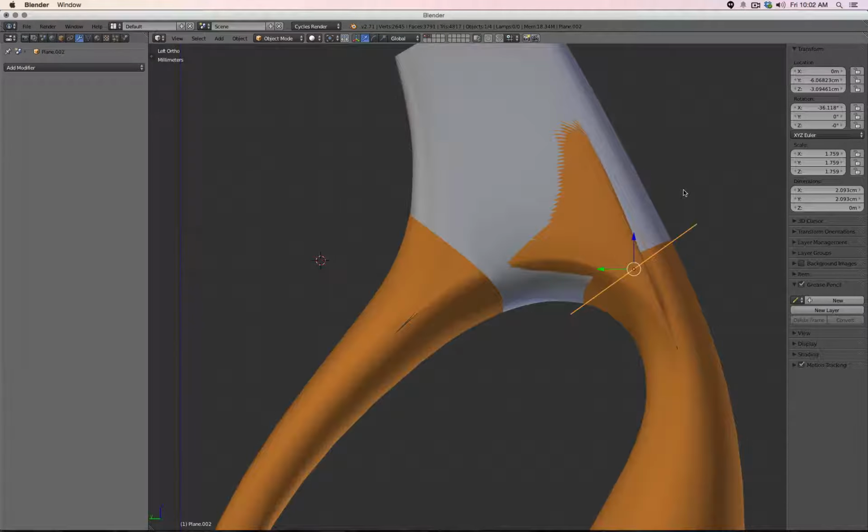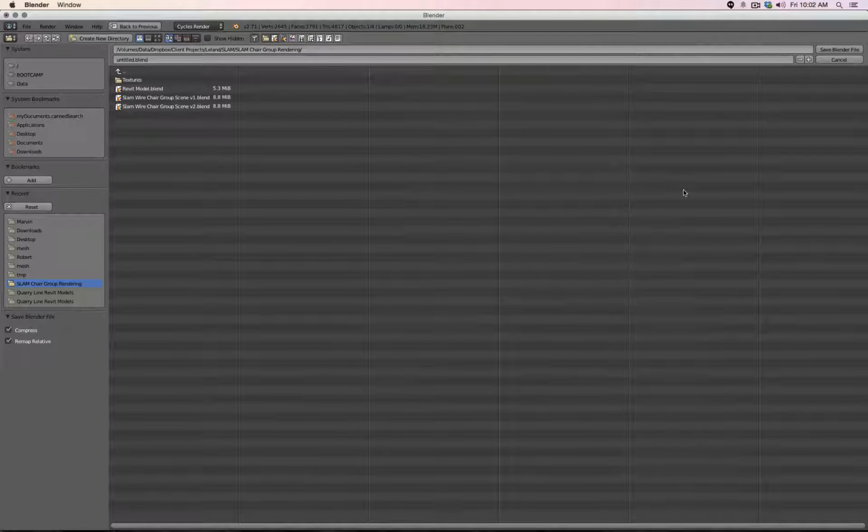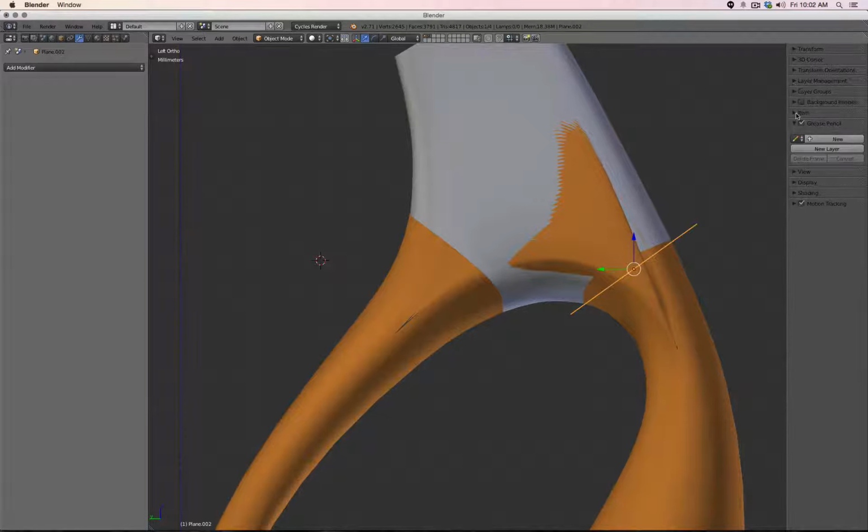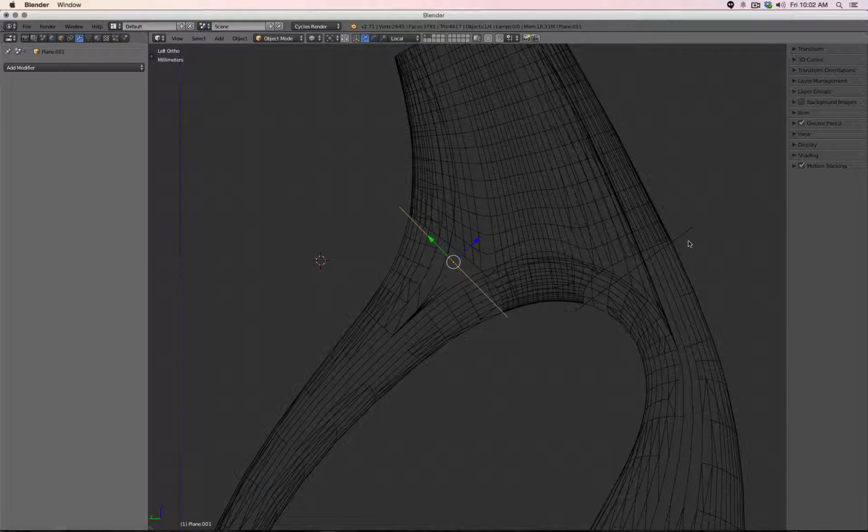And the main reason for that was simply I can go to my transform, set this one to local, and you see the local direction. I can actually save this one in Blender. So I go to local, to transform orientation, select the local vector and say plus.